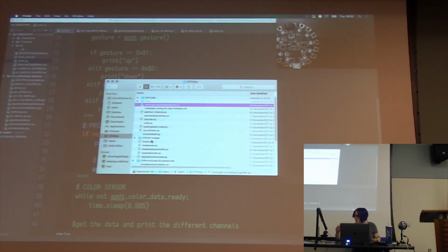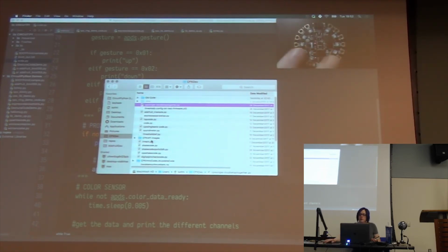There's an on-off switch and some more touch sensors built into Gemma. Those are the two cheaper versions of the board, but really this one is the ideal one for beginners. Metro is definitely on the far end of you don't want to get started with Metro. Metro is far more complicated because you're wiring literally everything that you're going to use. So the SDA and the SCL on these two sensors is swapped, so I am rewiring the breadboard.